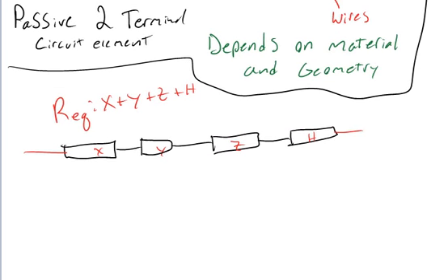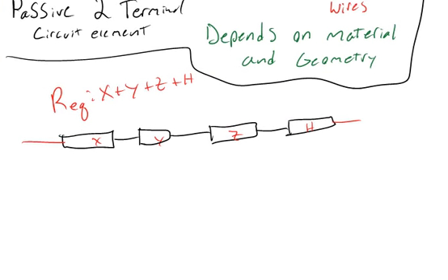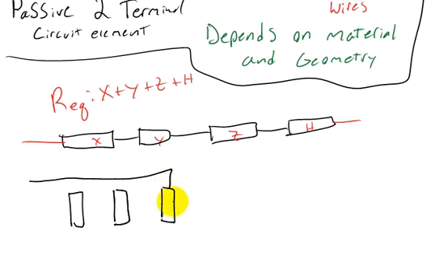Your problem comes when you start dealing with a parallel resistance. Parallel resistance is a bit harder, just because you have more to do and more to think about. But parallel resistance, like I said, is we had these four resistors, and then I had some voltage across them, and this was X, this was Y, and this is Z. The equivalent resistance across these two red points here will be basically you add up their conductances.